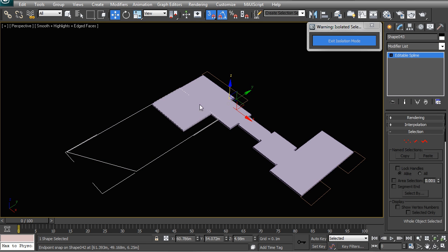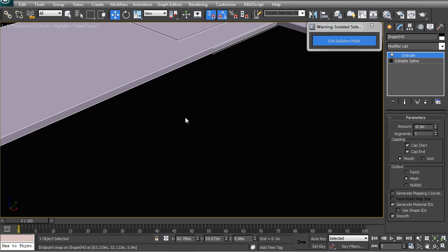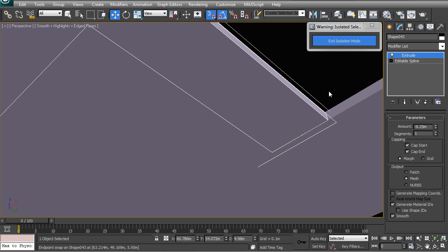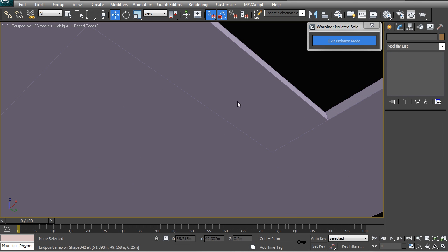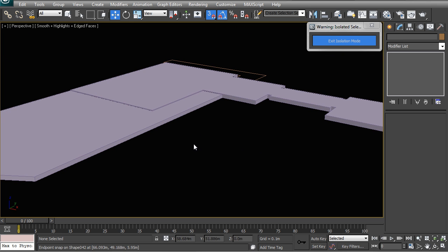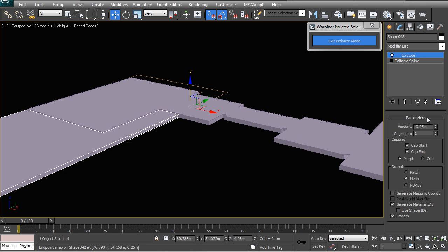And let's start off by just taking this extrude, dragging it onto these other objects. But instead of minus 0.3, it's going to be 0.25 so that the bottom basically lines up flush. If you have it 0.3, you're going to see a step here, which does sometimes happen if there is a floating ceiling below your slabs. So here you can now have that 0.25.